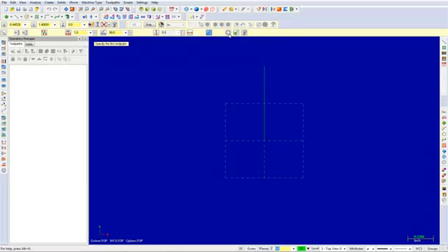Click the Unzoom Previous 5 button until the drawing comes into view as shown. Then enter a length of 0.15 at an angle of 180 degrees. Pick the line endpoint as shown and then select the Apply button.